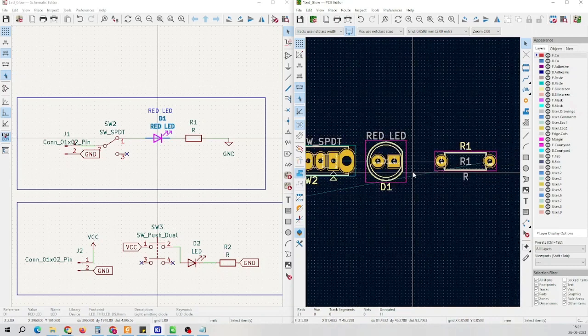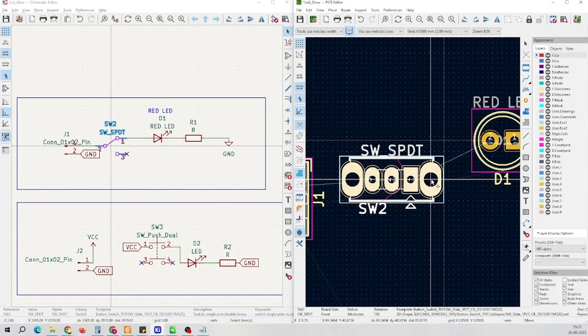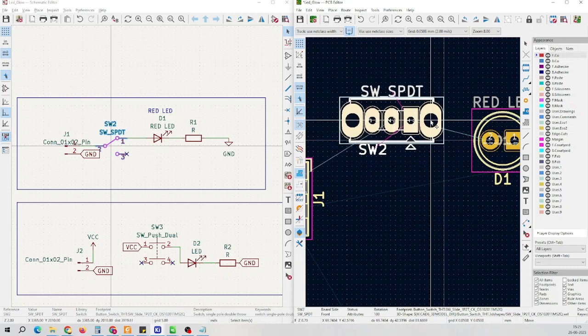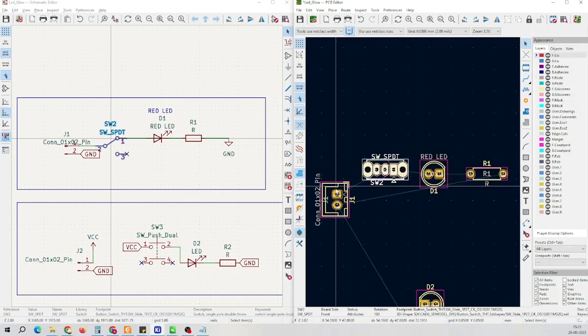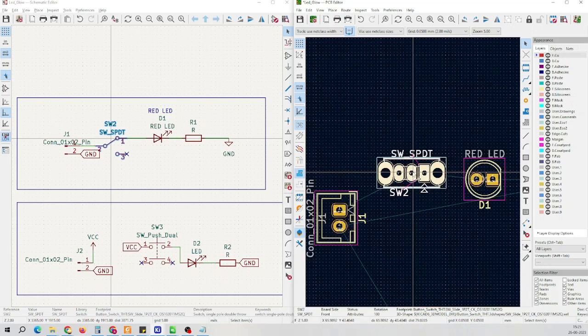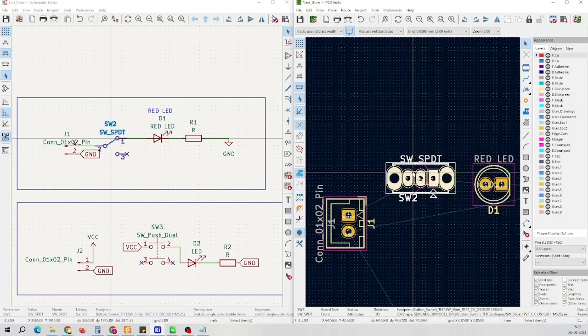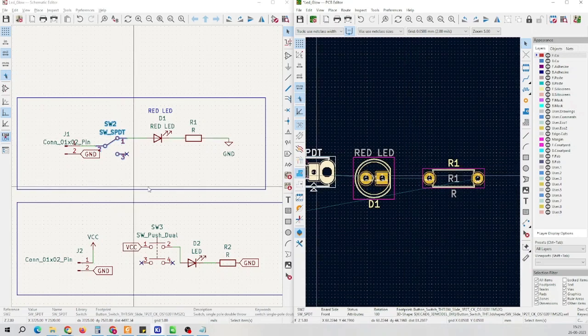So if I move this component, these wires will also move along, and these basically indicate the shortest path, and this is how the track will be moving from one point to another point. And we have to make sure that there is minimum crisscrossing between these points, because if there is minimum crisscrossing, only then the routing will be easier. Otherwise, routing will be difficult.